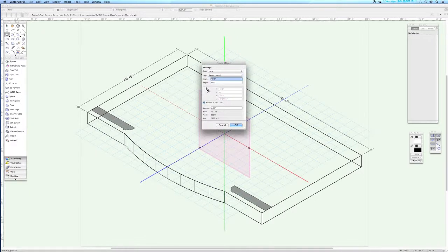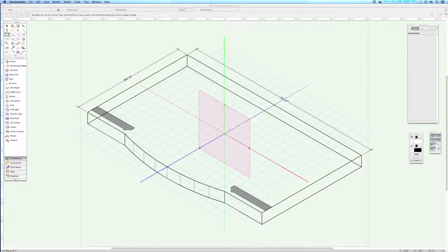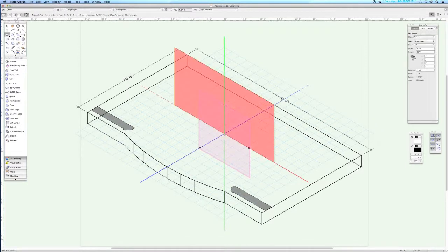So my proscenium is 40 feet wide, and I'm going to say it's 20 feet high. Now when I bring the mouse to center, it'll snap there, and when I click, it'll create a rectangle that is in the same orientation as this working plane. Now I actually don't want a full rectangle. I only want 3 sides of it. I want this vertical side, this horizontal across here, and then this other. I don't want the line that goes across the bottom.